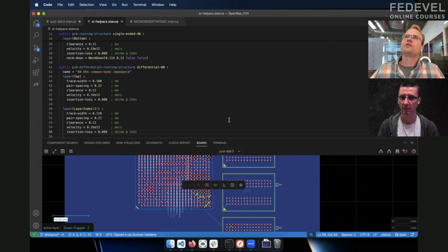And we built a lot of solvers so that writing code just becomes really productive, like this auto router, the pin assignment, supply chain integrations or Altium exporters, to just make the code more useful as a way to design things. So first, I can imagine one of the advantages is probably you can reuse a lot of stuff in next designs. Or if you need to modify your existing board, I guess it's going to be super easy because you already have almost everything. But even if you have normal schematic, it's easy because you don't have to redo everything.